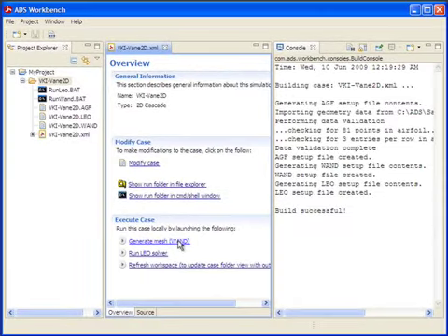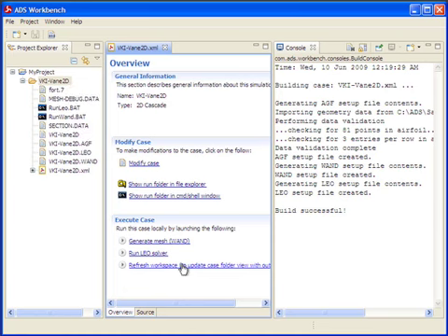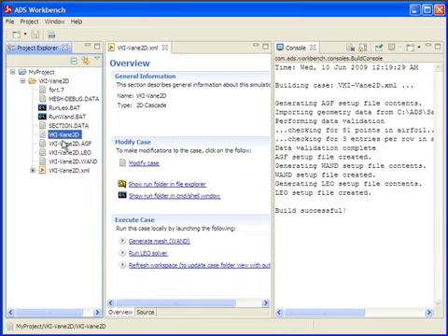So by clicking on the link, the mesh gets generated. It happens pretty quickly, you can see here for this case. And in order to demonstrate that it is run successfully, we'll refresh the workspace and look for the existence of an initial binary restart file. That is of the name VKI-Vane2D. It in fact exists along with some additional diagnostic information, and that tells us that we're ready to go off and invoke Leo. To invoke Leo requires both the restart file and the setup file.